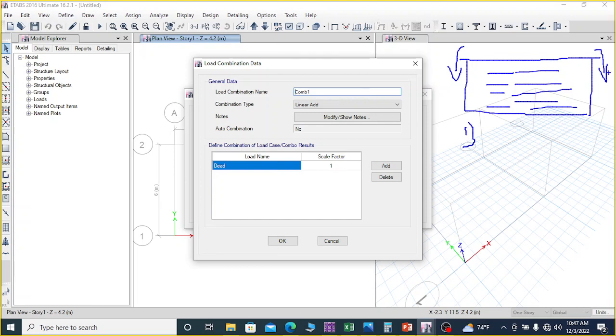This phenomenon will occur during the leakage test of the underground water tank. After the completion of the construction, we will not backfill the soil, so it will be left vacant for the inspection of leakage.